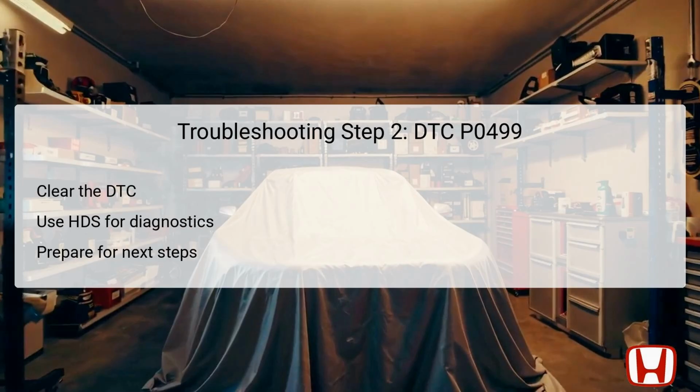The second troubleshooting step involves clearing the DTC using the HDS, Honda Diagnostic System, tool. This step resets the DTC, allowing the system to reevaluate the current state of the EVAP system without historical faults interfering. After clearing the DTC, you need to select EVAP CVS on in the inspection menu with the HDS.